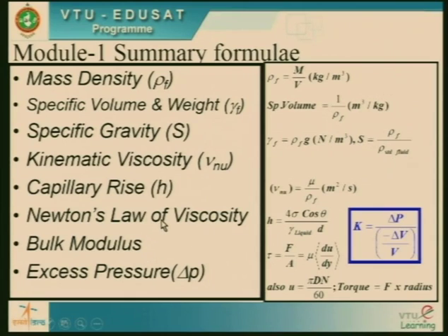Viscosity is nothing but the resistance to flow. It is defined by Newton's law of viscosity, that is tau, which is shear force divided by area, is equal to dynamic viscosity into velocity gradient, that is du by dy. Mind it well, mu is the dynamic viscosity.